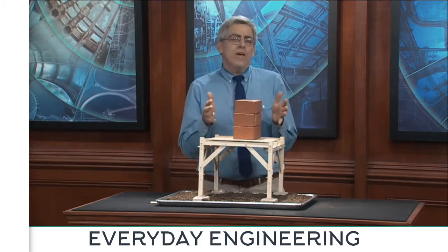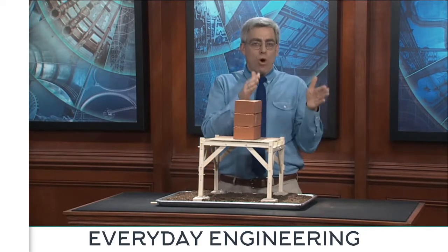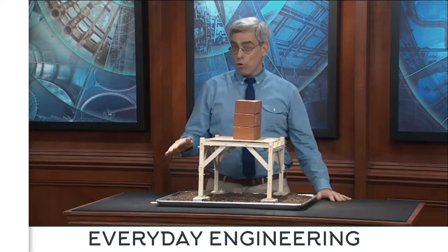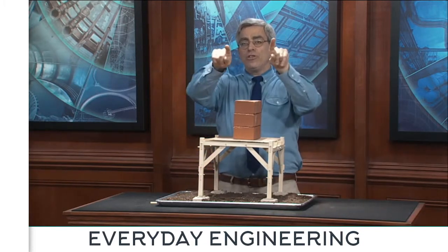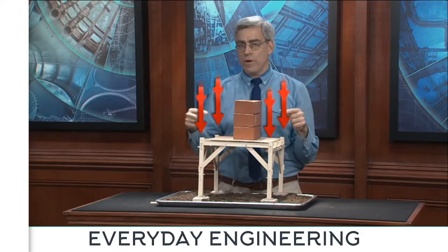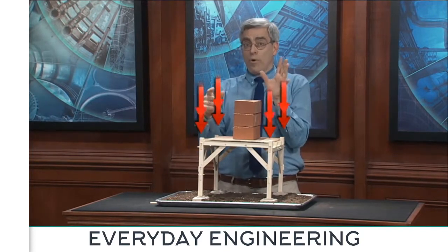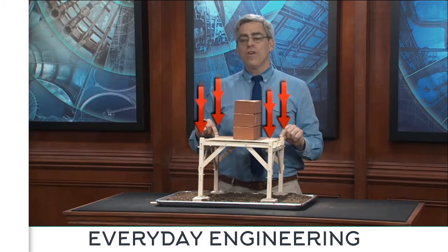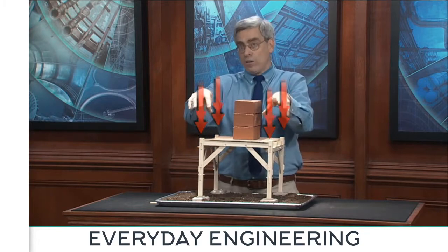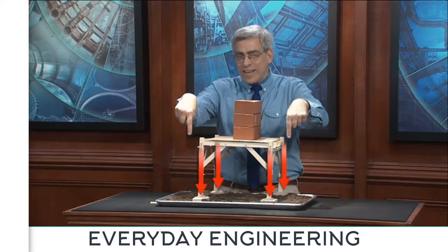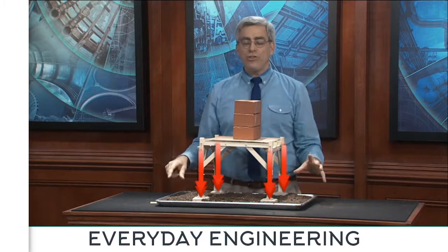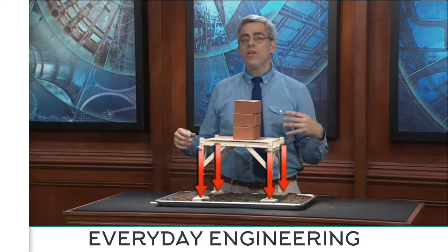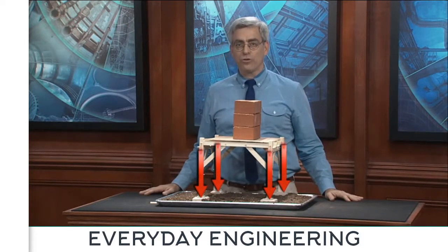Now, as a structural system, this timber frame is similar to the bearing wall system we looked at earlier in that gravity loads are carried by the floor beams in flexure, then transmitted out to the building's outer perimeter. But here, unlike the bearing wall system, the load is concentrated into the four corners of the floor system where it's transmitted to the columns. The columns then transmit it in compression downward into the foundation, and in this case, the foundation consists of four column footings in place of the wall footings that we saw in the earlier structure.